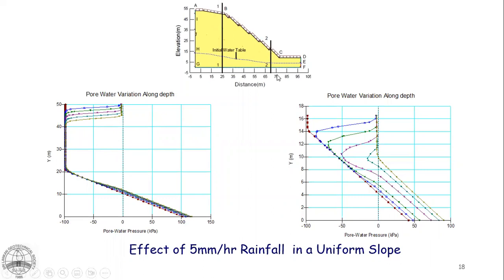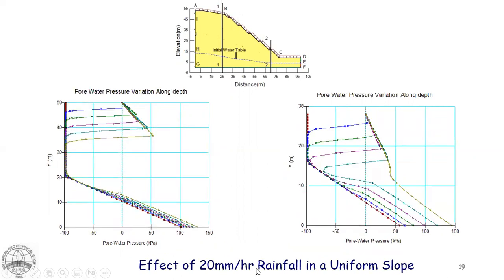In section 2, with the lateral downward movement, the alterations are much more. So with daily rainfall, the matric suctions were first lost up to that, then that, like that. And at the same time, there is a greater rise of the groundwater table. So with the prolonged rainfall at these sections 1 and 2, the pore pressure regime is subjected to this range. So we can model this and we can incorporate this in the stability analysis thereafter.